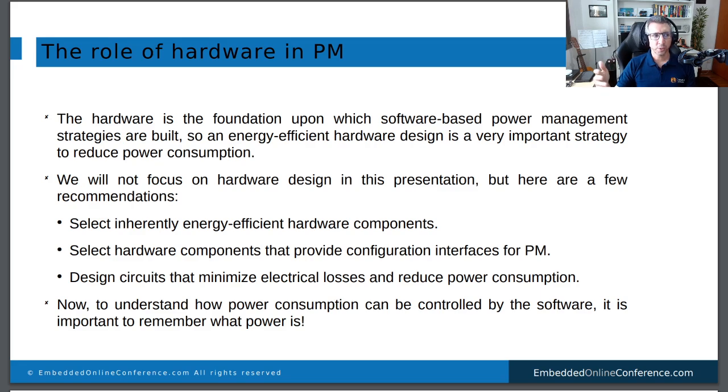Even a resistor in the wrong place on the board might cause power consumption problems. So thinking about the hardware is very important. This presentation is not really focused on hardware design, but we have to keep that in mind. We're going to focus here, of course, on the software side, but to understand what we can do on the software side to manage power, we have to understand how the power consumption can be managed.